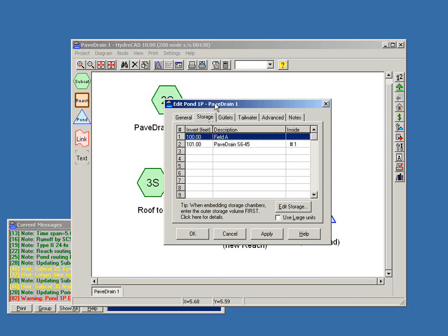Before I do that, just to reinforce, the Pavedrain system itself is able to handle the entire volume of a storm. That's the beauty of it: you could take your 100-year rainfall event of 4, 5, 6 inches and retain that entire volume in your stone. And it would infiltrate, in seconds too.